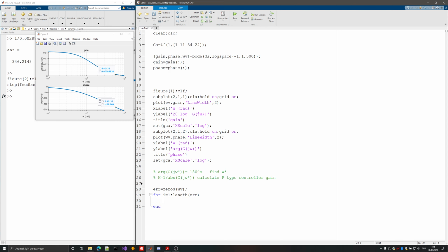And what I'm trying to do is I will use the first step here in order to get the omega. So you might say, why aren't we searching exactly for -180 degree? And my response will be that you might not have that value, but you might have a value that's close to -180 degrees, as in the case of where you can see in the graphic that we have -179 point something. So I want to approach the vicinity and I want to just use an approximate value. That's enough for me. So that's the reason why I should do something like this.